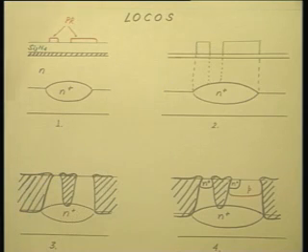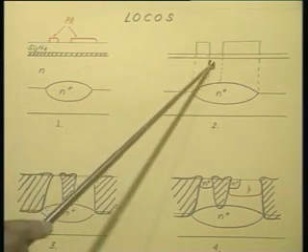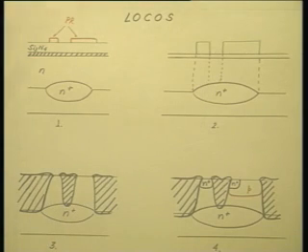Reactive ion etching is usually adopted, so that you have highly directional etching. Okay. So, this is called recessed oxide. Recessed oxide, that is, you first create a recess in silicon and then you oxidize it. So, you etch it down to a certain extent and then you subject it to oxidation, so that your calculation is such that the top of the oxide comes only up to the surface.